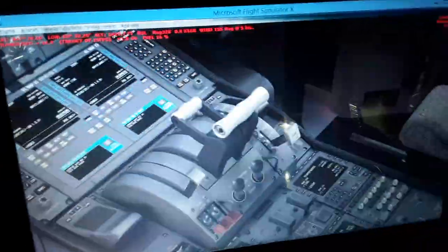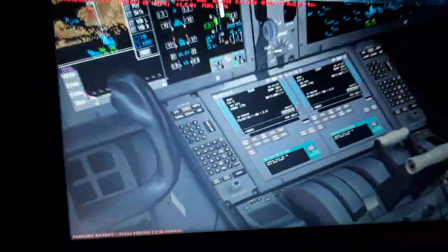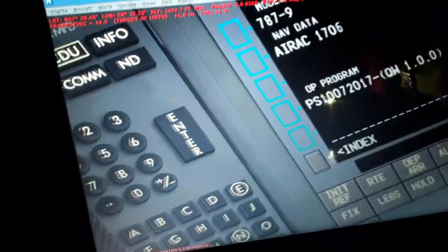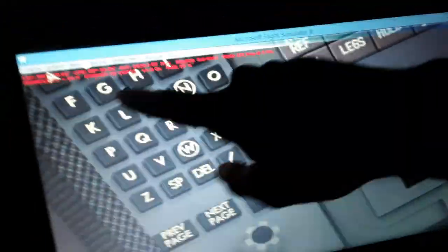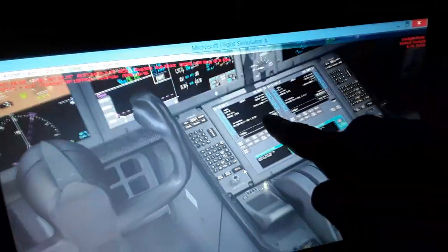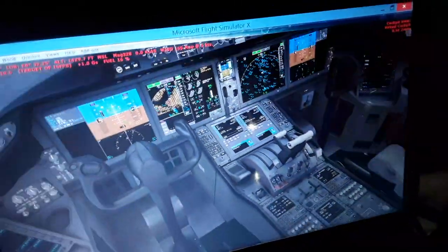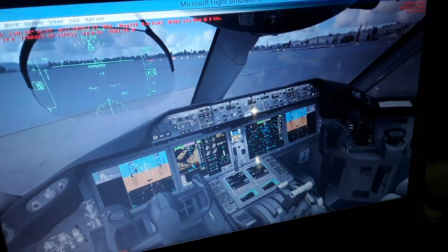Also in the flight management computer over here, as you're gonna see later when we're gonna create the flight plan over here. So you can see the alphanumeric keyboard here for inputs, and the modes we're gonna select. Also the autopilot flight director system panel. So I insert all the data as I told you: takeoff gross weight, the left and the right wing, fuel on board 30%, center tank 10%, 30% the left wing, 30% the right wing.